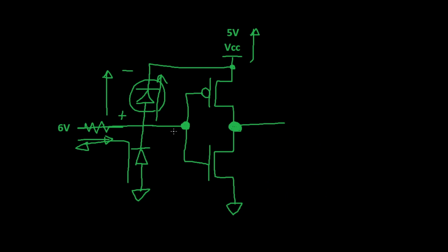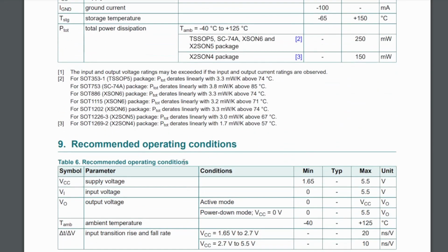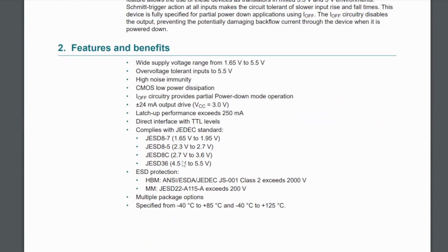One thing that's important to bring up whenever we talk about the ESD protection on the input of a logic device is that the logic ESD protection is very weak. Let's take a look back in that same datasheet. When we go back to the front page and look at the ESD protection, it lists HBM at only 2000 volts. That may sound like a lot if you're not familiar with ESD protection, but standard system level protection diodes are going to protect from 8 kV or more. This is definitely not enough ESD protection for system level applications.